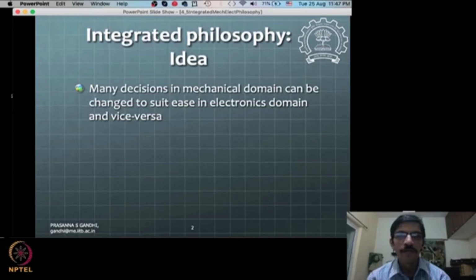Now this complexity of all these mechanical chains of driving the cam and affecting the fuel injection can be taken care of by using the electronic fuel injection system, where by the digital command of some electronic interface, the fuel will be injected into the system.